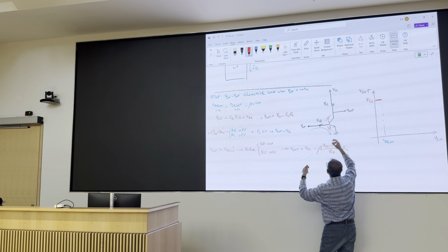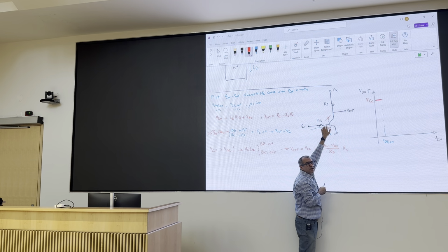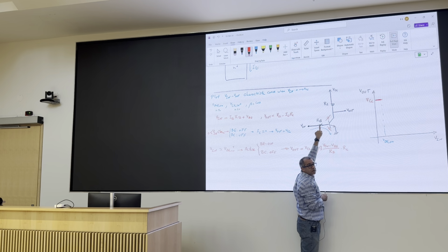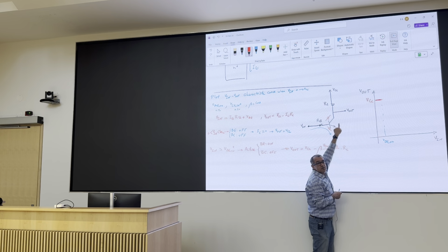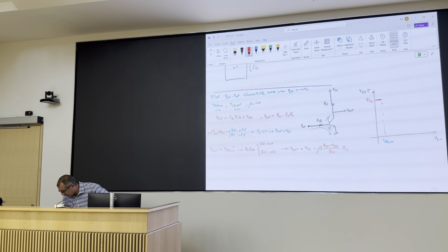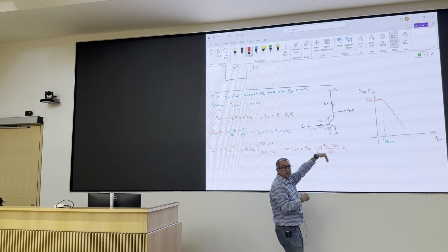How does that happen? Well, a larger Vin here, larger IB, because this voltage is more or less fixed, it's 0.7 volts, right? So a larger voltage here, a larger current through RB, meaning a larger current IC. Larger current IC means that the voltage across the resistor gets larger and larger. So this top end of the resistor is fixed, this end must go down. So what you expect to see, or what you see, is this. Right? As you increase Vin, Vout starts to drop.